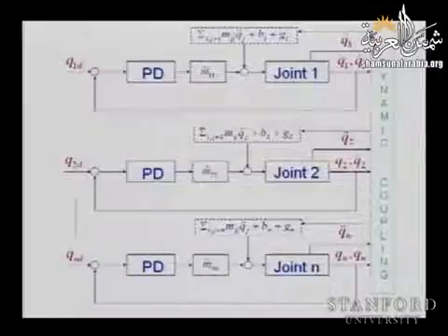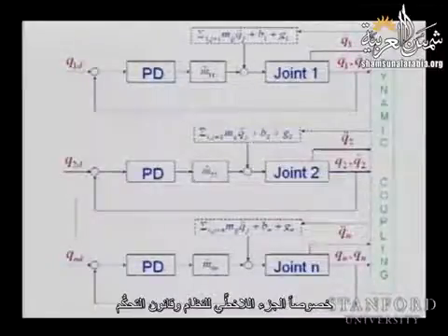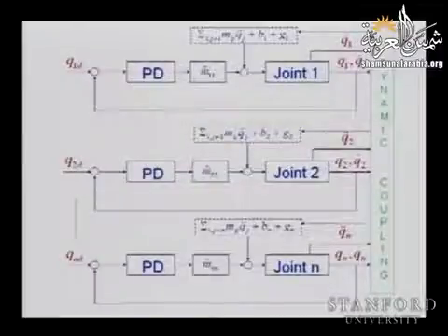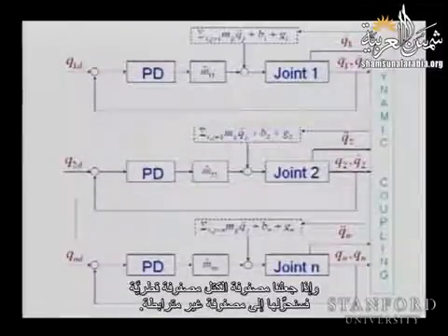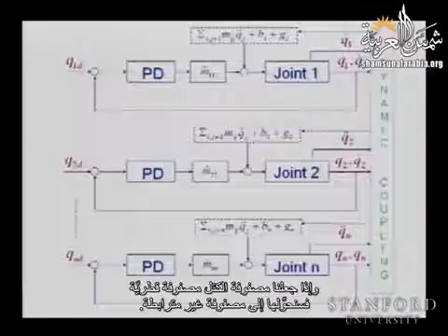Oh, I'm sorry. You're sitting so far from the left. If you use a model of your plant, especially the nonlinear parts of your plant, in your control law, effectively you can turn it, and also if you diagonalize the mass matrix, you turn it into a decoupled, very simple 1/s² plant. Yeah.